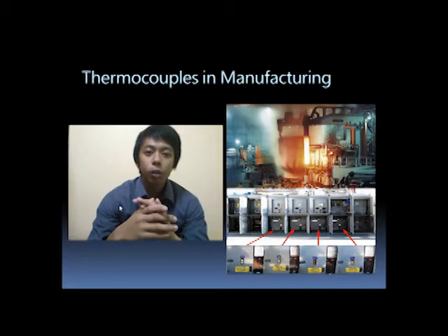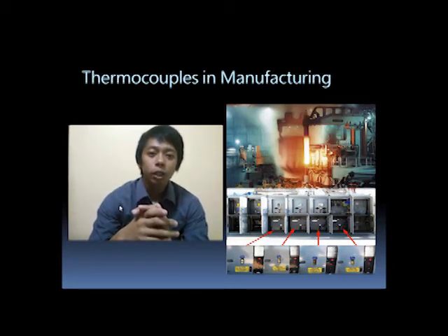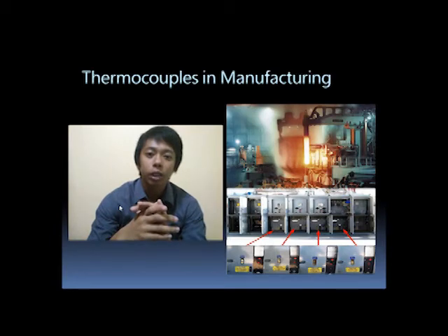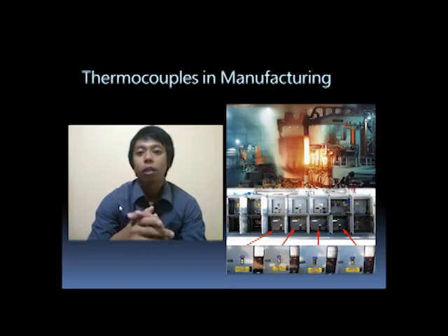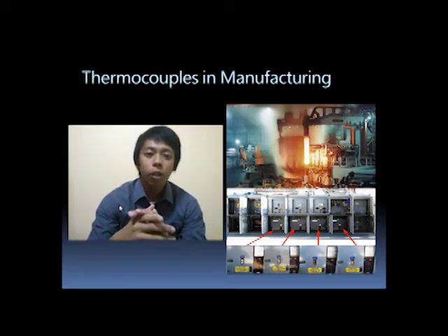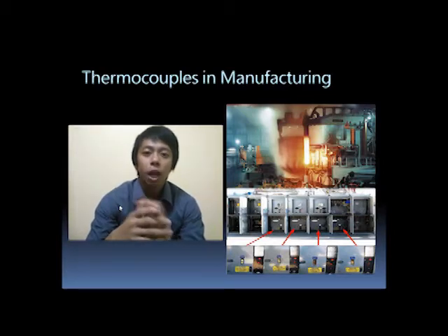Because of the thermocouple transducer's capability of handling very high temperatures up to 2300 degrees Celsius, one of its most important applications is its extensive use in the steel and iron industries to monitor temperatures and chemistry throughout the steel-making process. Thermocouples are regularly used in the electric arc furnace process to accurately measure the temperature of the steel before tapping.